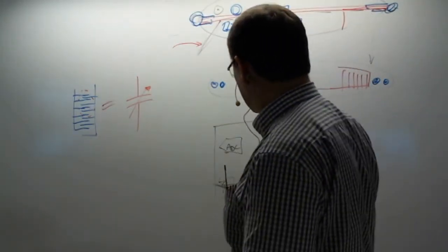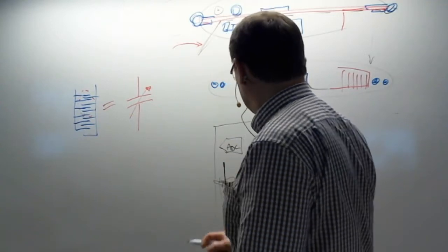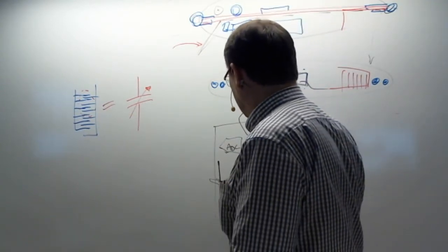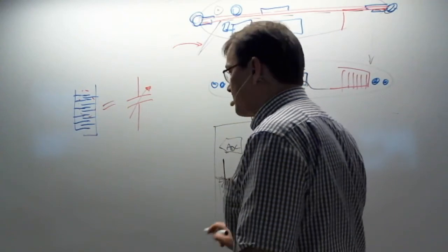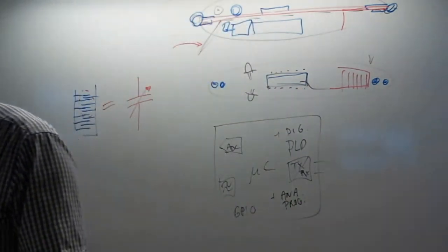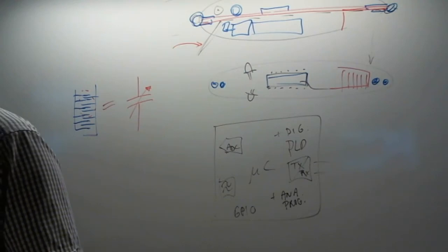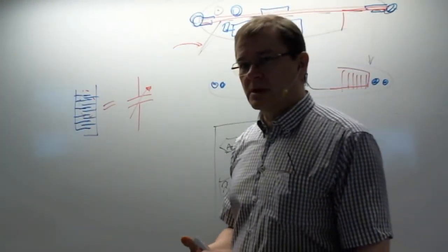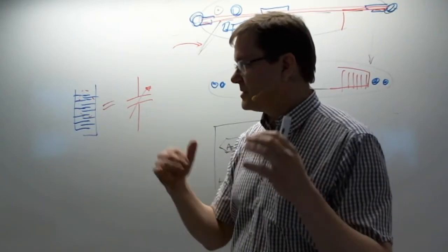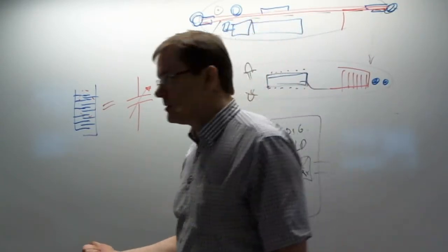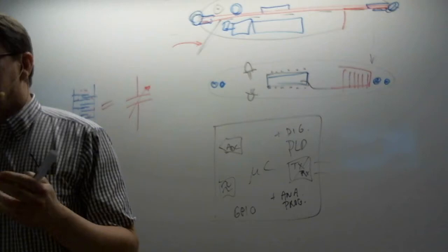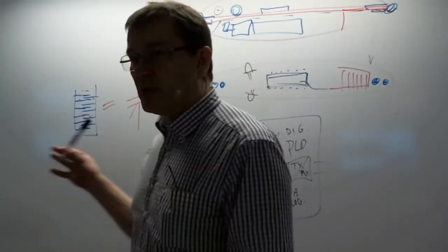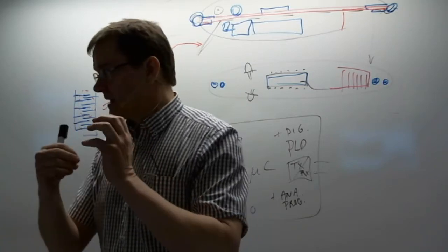And of course, it also has the microcontroller core with all kinds of stuff, and really flexible GPIO. For digital I/O there are no real restrictions on which pins you can use. You can use any pins. For analog I/O you can use only a couple of ports, but that's already a lot of flexibility.